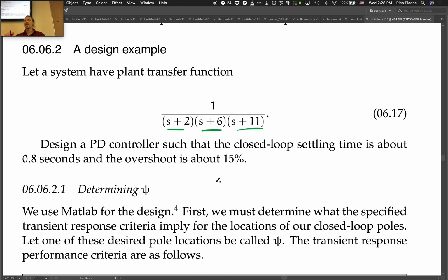But on an exam, if you do the correct procedure and you get within 10%, that's pretty good. If you get within 10% the first time round, I would say go back once and tweak the gains and see if you can get a little closer. But once you get within 10% and you've done one iteration through, that's probably good. You don't need to keep going. Keep going if you're not within 10%. Yeah. Good question.